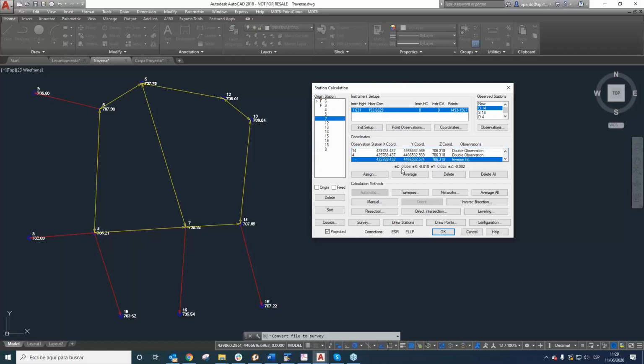As I said before, we can find here the difference between different results. In this case, the distance error appears as 5.6 centimeters. Now everything is calculated. Now it remains to compensate, for example, the coordinates. We are going to say that the coordinate the application is going to use is the coordinate that is selected in this window, in this part.